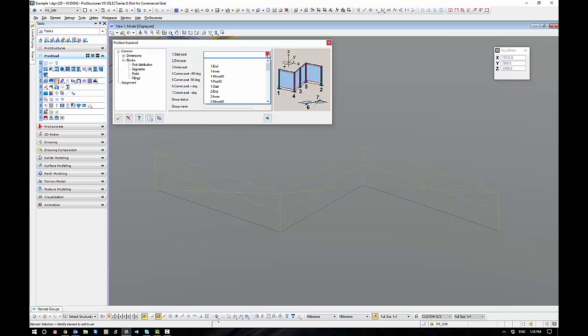So I'm going to kick off by starting with a start post, and now these are the standard Bentley blocks. Now they're not really a block as such, all they are is a drawing with a couple of objects in that are set up to work with this function. So I'm going to go and find the start post, and you can see it drops it straight in, and you can see here that it's just a series of ProSteel objects that have been saved off as a drawing and called in here. Now as we insert additional objects, it's going to try and continually connect things up for us.